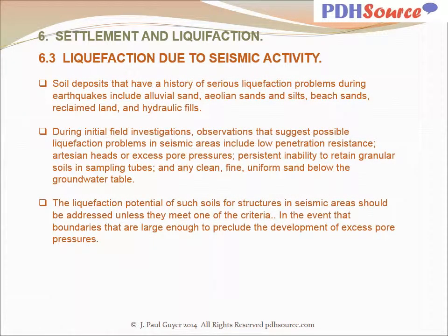Soil deposits that have a history of serious liquefaction problems during earthquakes include alluvial sand, aeolian sands and silts, beach sands, reclaimed land, and hydraulic fills. During initial field investigations, observations that suggest possible liquefaction problems in seismic areas include low penetration resistance, artesian heads or excess pore pressures, persistent inability to retain granular soils in sampling tubes, and any clean, fine, uniform sand below the groundwater table.